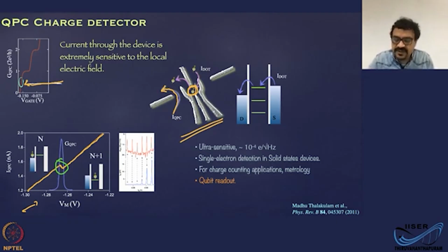So just to understand the process a little bit more clearly, when you sweep the voltage, this is Vm, whatever is labeled there, you are going to push this electron out because you are creating a negative electric field which pushes the electron, or you are basically increasing the energy of the electron states inside the trap, inside the dot.